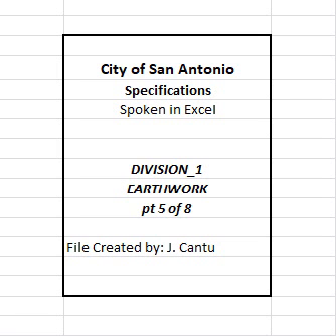When measured by the cubic yard in its final position, this is a plan's quantity measurement item. The quantity to be paid is the quantity shown in the proposal, unless modified by change order. Additional measurements or calculations will be made if adjustments of quantities are required. Shrinkage or swell factors are the contractor's responsibility. When shown on the plans, factors are for informational purposes only. Measurement of retaining wall backfill in embankment areas is paid for as embankment, unless otherwise shown on plans. Limits of measurement for embankment in retaining wall areas are shown on the plans.